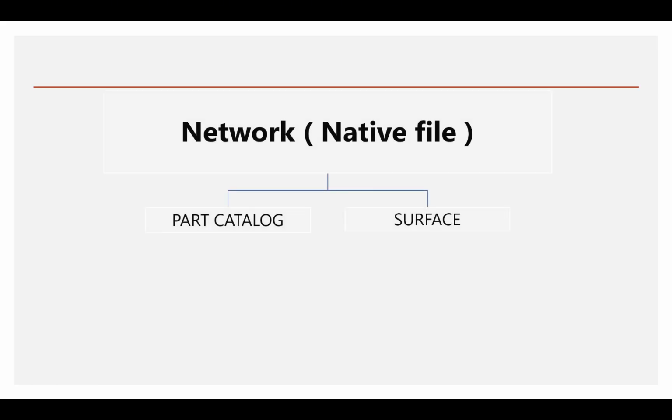We will need the part catalog, which the parts themselves are used from. If I have IFC structure elements, I need the part list which is used for these certain structure elements. If I don't have this part list, I will have a lot of glitches and a lot of problems editing the file. And of course, I will be needing the surface.